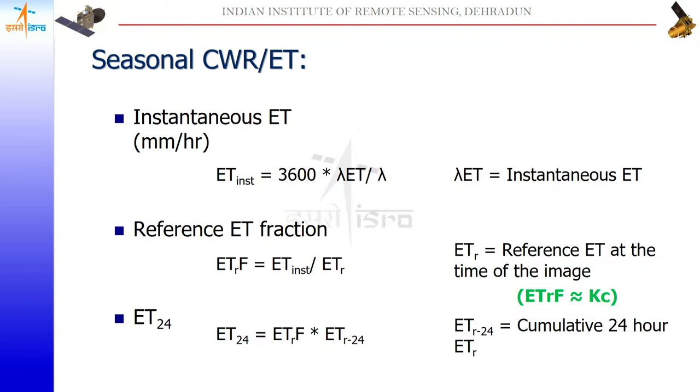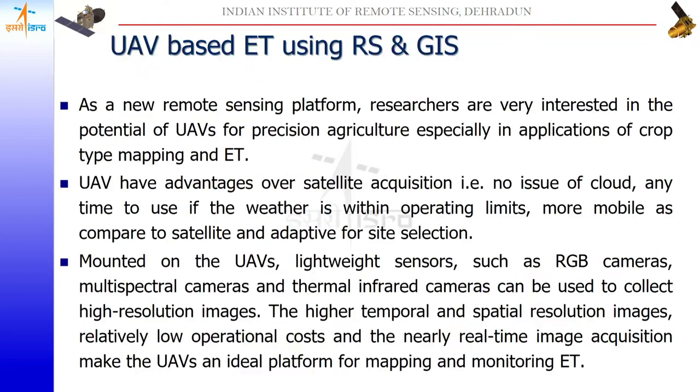As we get the daily basis data sets, we further integrate them maybe through an interpolation technique, because remote sensing data sets have a defined temporal resolution, maybe every 8-day or 16-day data sets. In between, the gap filling is done through interpolation. There are a number of interpolation techniques, so we can use linear interpolation or weighted interpolation, just to define the values of evapotranspiration rate for each and every day.